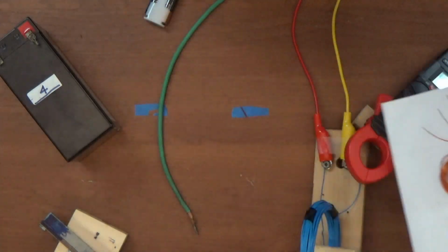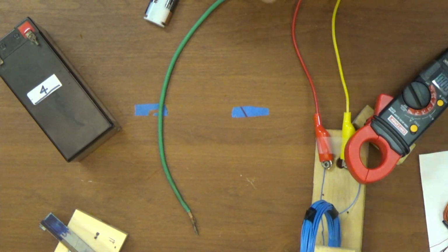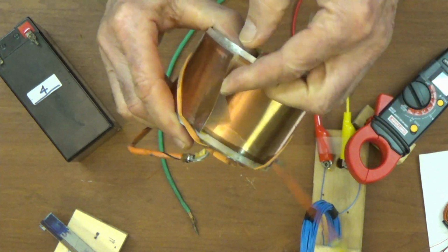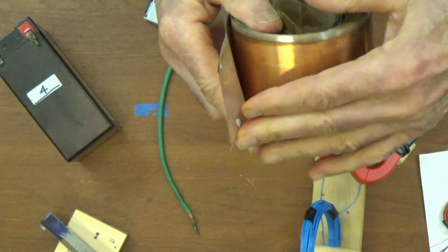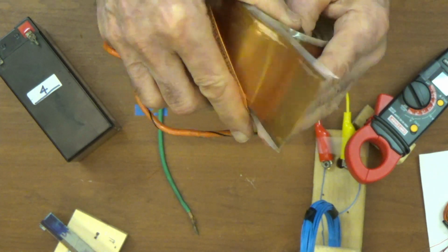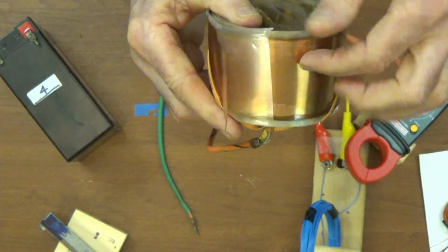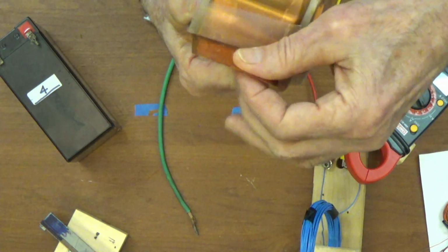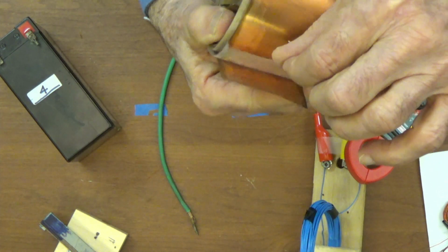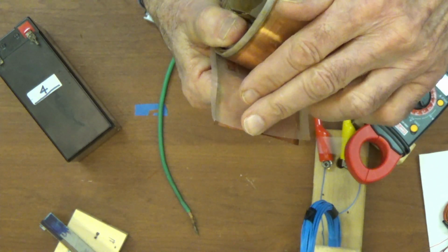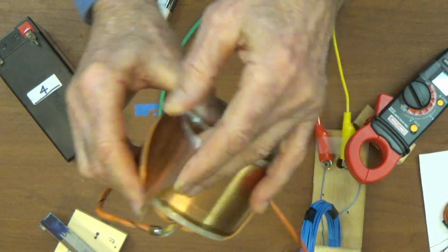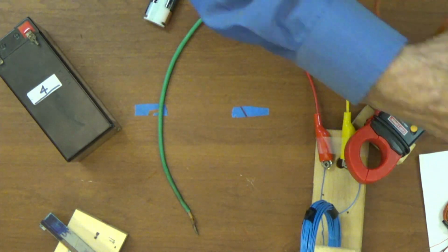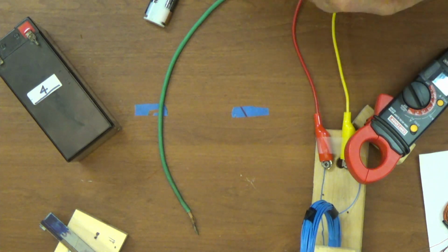They're not all round. For example, here's a special case of magnet wire where it's a sheet. It's a sheet of copper, and it has insulation on it, and this kind of double insulation over protecting it. There is a coating on here, I think, but in addition to that, there's just this sheet of special material. So this is a very specialized kind of magnet wire. Typically it's round, but it could have other shapes.